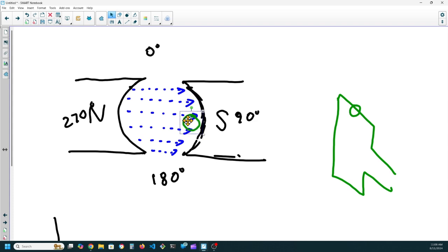And when we get to 90 degrees, we're running perpendicular to the lines of flux. We are generating the maximum amount of voltage we can generate with this generator. That's 1. And then we come back to the other side. There's 135 degrees, and that's back to 0.707. And then we get to 150 degrees, and that's back to 0.5.